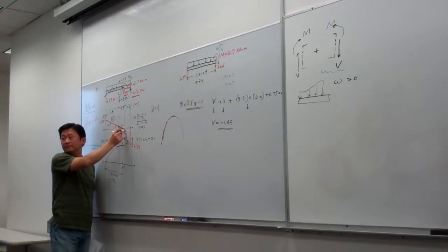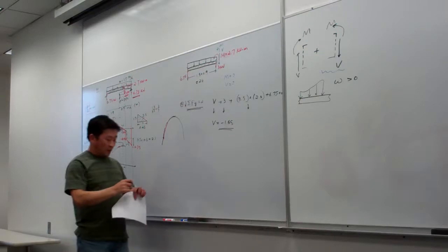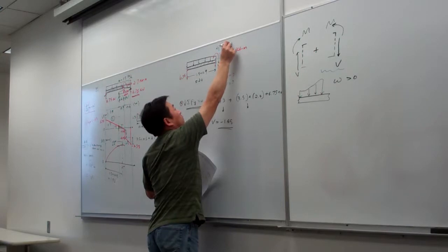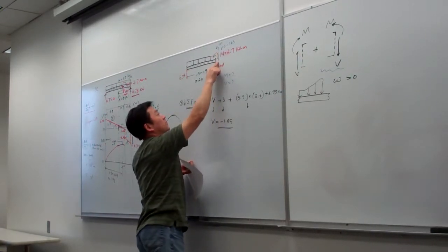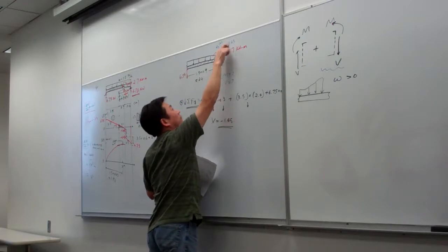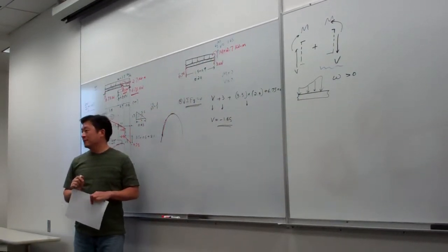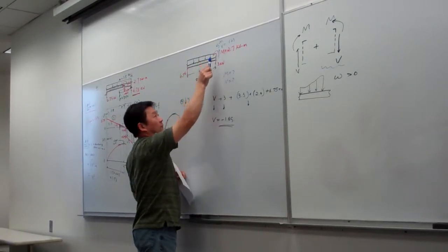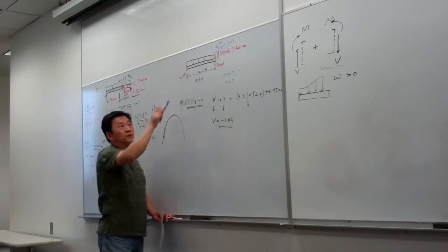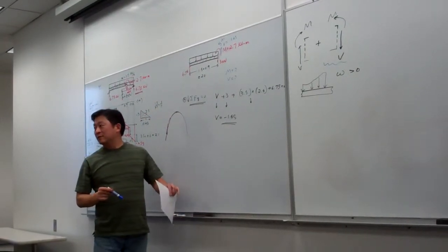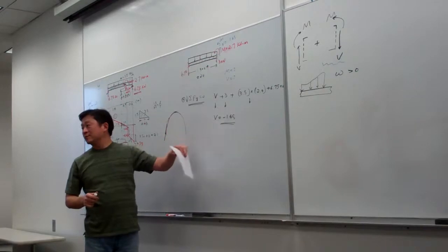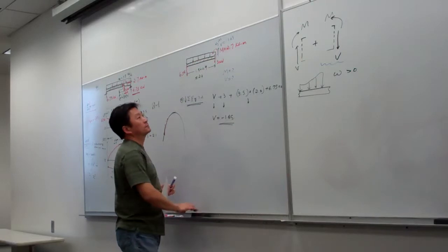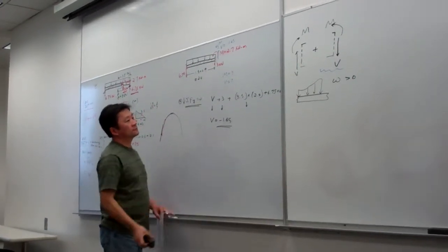Got it? You mean on your sum of Fy? Yeah, so which means here I would say V equals minus 1.65. So that means equivalent to say V is actually upward like that. Okay, so at this section, V is acting upward with that magnitude, per our calculation. Okay, because earlier I assumed...